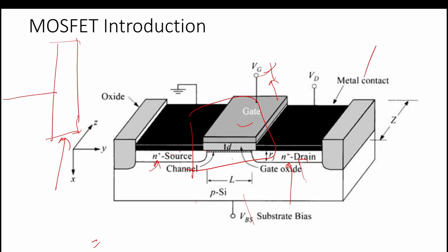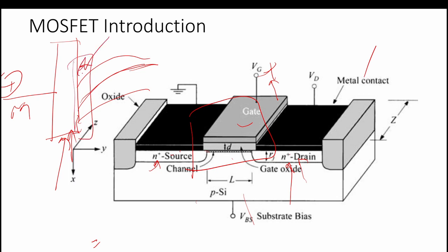This is the metal Fermi level, and as we apply the positive bias here, what will happen is that at the semiconductor and oxide interface, the bands will bend like this. In this region there are so many electrons, there is a sheet of electrons.